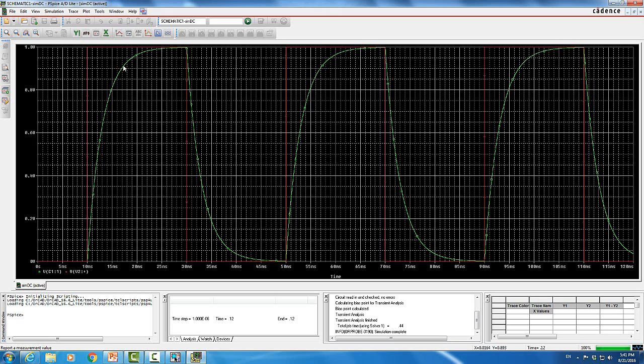Anyway, so you have different parameters to measure the time rise and the time falls, and so you can see that you are almost reaching the final value. This is not 5 tau, 20 milliseconds, not 5 tau, it's much less than that. So anyway, that's what you have. And then when it drops slowly from 1 to 0 volt, the voltage across the capacitor will have some time to reach the final value. So, and that's the end of the simulation.